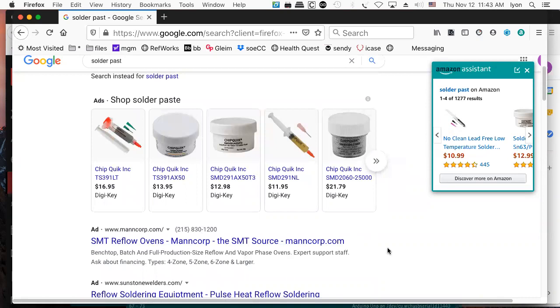And then, so when you heat it up, it goes solid. Is that what you're saying? Like after you heat it up? That's correct. It's like a third alloy. Third meaning, well, let's say you've got the copper pad, you've got the components material, and then you have this third alloy with the low melting temperature. And when it melts, it's conductive, but then it solidifies rather quickly.